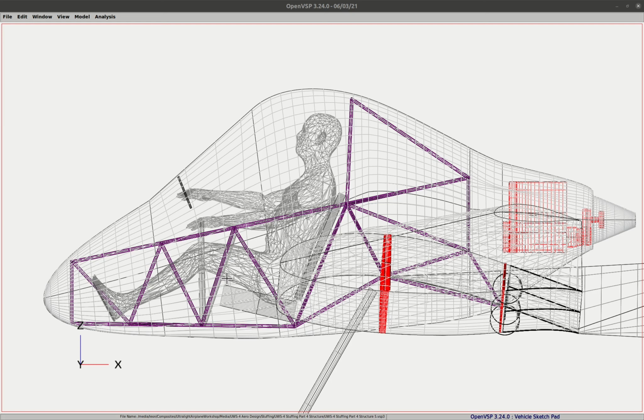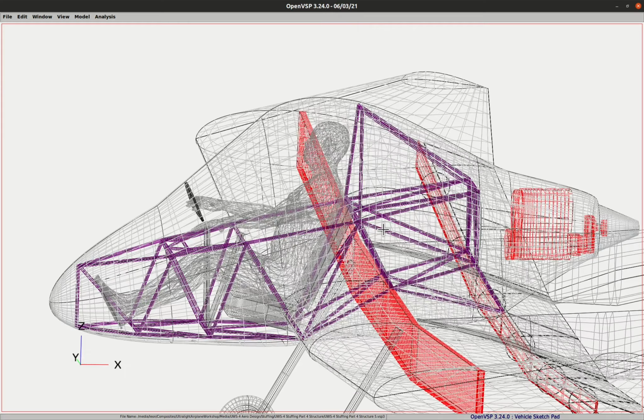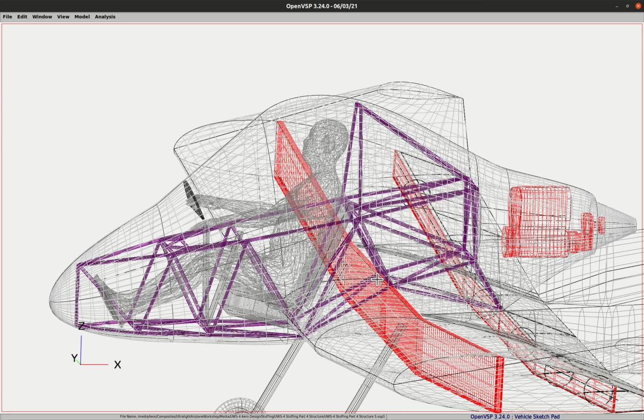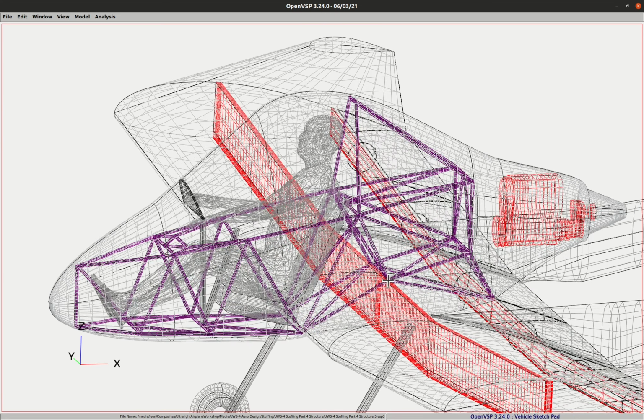I guess a good location to start talking about this is where the wing attaches to this fuselage. So again, this red area here is our front wing spar. This one back here is a rear wing spar. Like I said before, there's going to be 3 attach points. I want to be able to detach the fuselage and the wing. So my initial thought on this design is the attach points for the fuselage to the wing are going to be right here on the main spar.